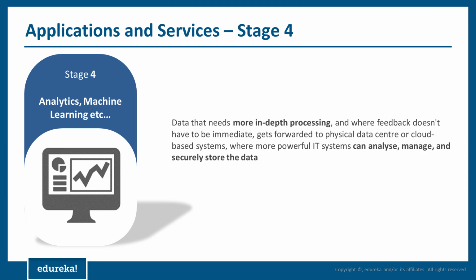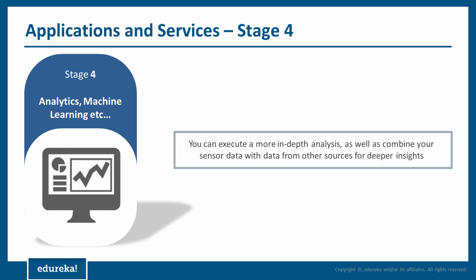Okay, so you want to analyze, and here it is a little deeper analytics, not just whether the temperature is above or below 104. It's identifying the patterns within the data. It's not just a single variable. There'll be multiple sets of data coming from multiple different sources, and together they generate different types of patterns. To give you a very simple example, a motor is there, constantly sending its data. Now, when you constantly collect the data and try to see those patterns, you see some patterns emerging which show that the inclination of the spindle is a little disoriented. Secondly, the vibrations have increased. Third, the temperature is slowly rising.